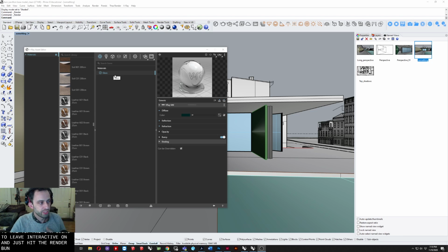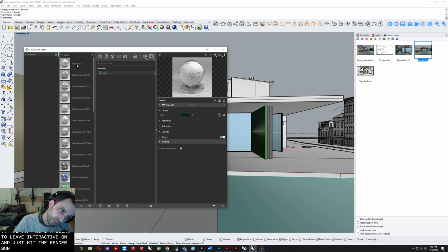So oftentimes if you see a render, and when you're doing a render the glass appears to be essentially pitch black, that's probably why. It's not being read as a solid. So light is entering, but essentially refracts infinitely until it is complete blackness. So in that case, let's see if they happen to have a glass in here. So fake glass is probably the one to use.